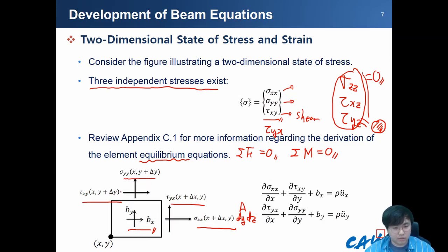And then this shear stress is related to the x direction forces, so the length is equal to dx, and then the thickness dz. And then the change of the stress is related to dy, so you should add those kinds of relationships. It is because the changes of the forces are related to the x derivative, and the shear stress changes are related to the derivative in dy.